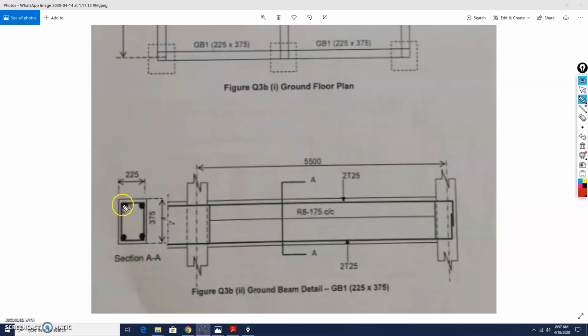Next, we are going to calculate for the stirrup. So the stirrup is here. It is made from 4 sides of reinforcement. If you look in this diagram, it will have 2 anchorages. So first, we are going to determine the length for one stirrup. First, for this side, the length is 375.